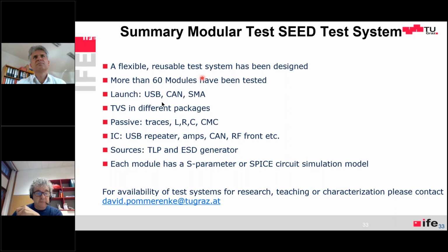Do you have varistor models? Yes, we do have varistor models. For some of them, one can make more. Varistors are usually not that difficult to model, but we never intended for surge testing. A very simple reason: our characterization system cannot characterize at the current levels which are needed for surge. We would have to take a surge generator. We have surge generators, but this is sort of not the question we have been asked. In principle, it can be done, but it's something we have not approached.